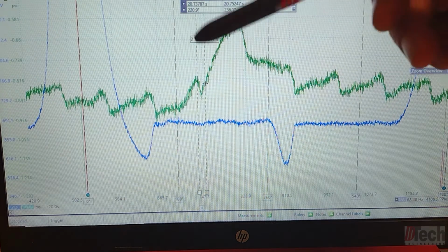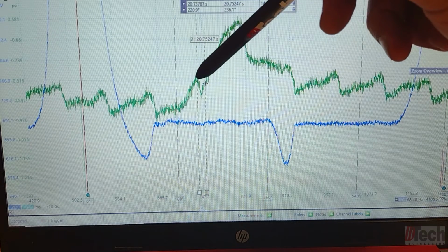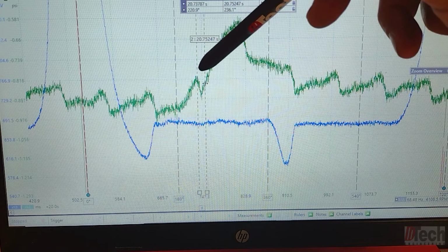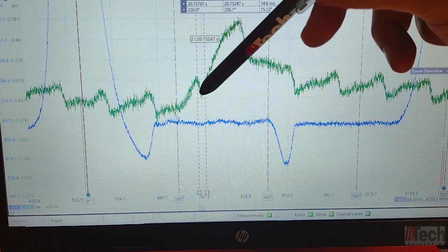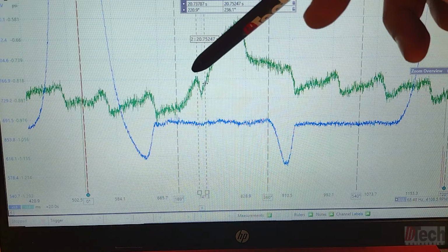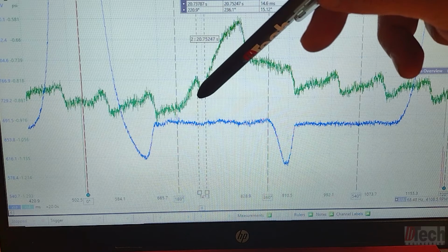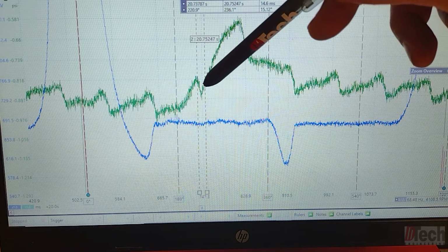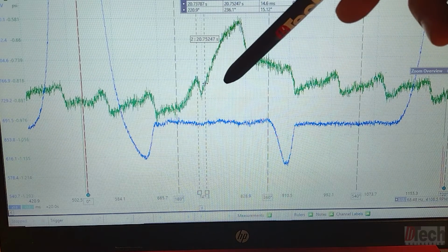You can see this is where I was talking about how it gets cut short. This is the same time distance, I guess, compared to this one, where almost halfway it gets cut off and then pressure starts to go up. Anytime I see that, where in time the pulls get cut short, it's due to introduction of positive pressure in the intake manifold, and you're only going to get that through a leaking intake valve